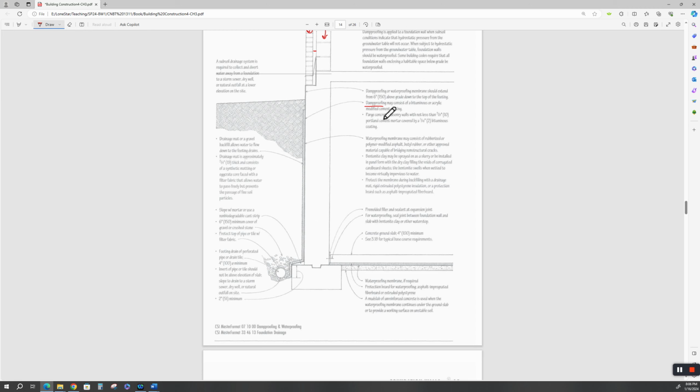He defines damp proofing may consist of a bituminous or acrylic modified cement coating. I would be very suspect about coatings. Everybody sells something that's supposed to be the greatest thing since sliced bread. Waterproofing membrane over something like a bitumastic coating, like coal tar epoxy or something like that, it's probably better. Waterproofing opens up a whole area of expertise.